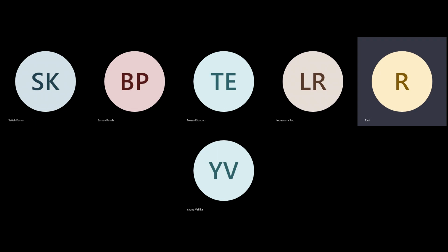Multiple site rows cannot be done in a single block. But as a single chip, if there is a requirement like that, basically for high performance, then you'll have to create a separate voltage domain for that. The voltage supply can be the same, but it has to be a separate block, and with a power ring, because the mesh pitch, everything will change. So that should be a clear-cut answer that it is not recommended, and I don't think any of our chips will allow that.